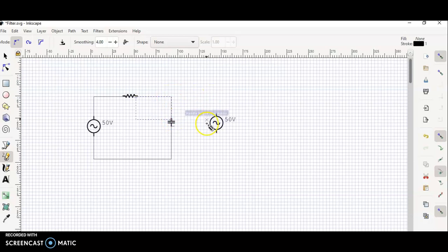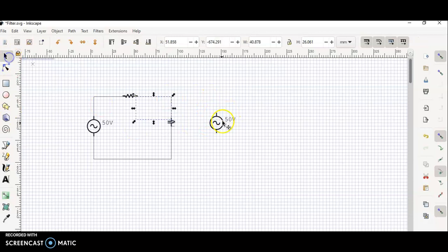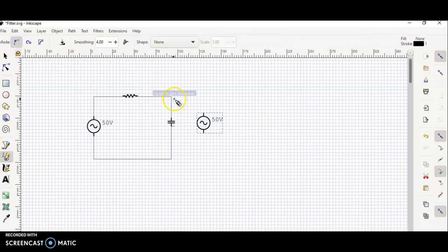Then which one is connected? The AC voltmeter is to be connected, which is parallel to the capacitance. So again we have to use the freehand tool, and take the meeting junction of the resistance and capacitance. Just here one click, the red line appears, here one click, again one click, at the end of the AC voltmeter double click. Okay, then it is stopped.